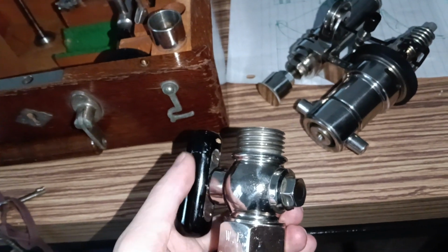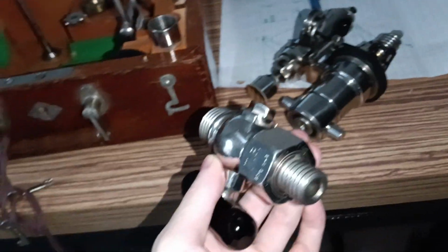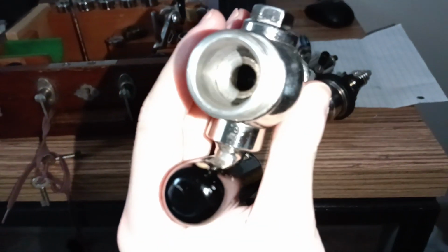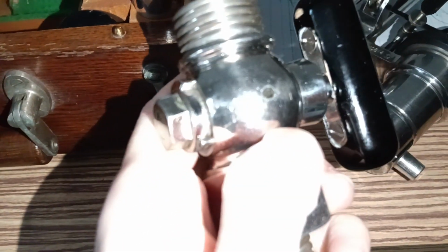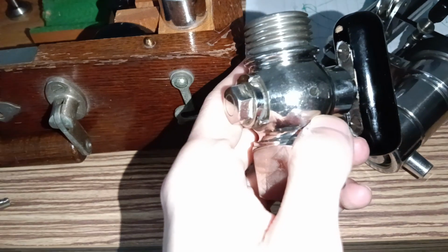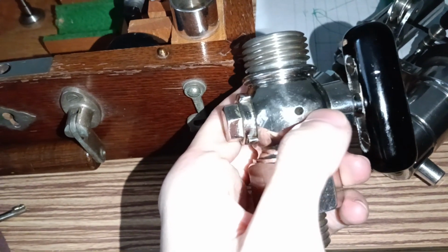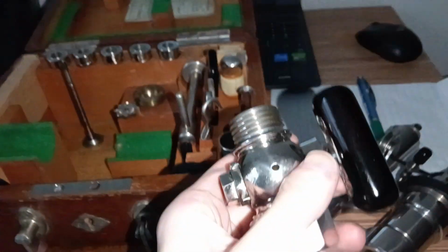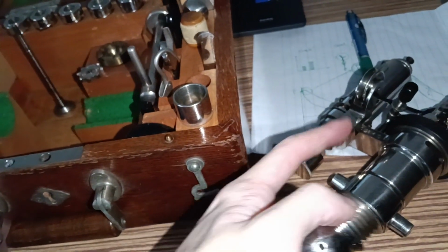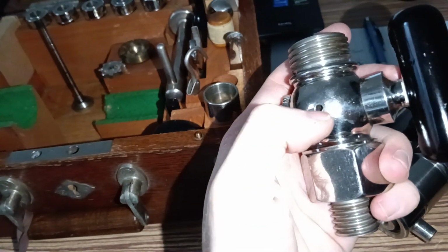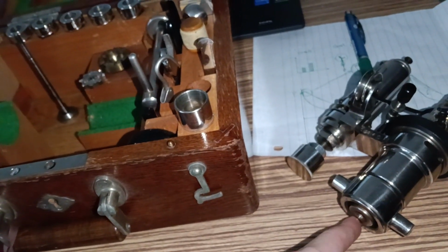When connecting, you connect this to the engine indicator cock first, this one to here, then open this one here. This is just another kind of indicating cock, but I don't really understand it. And actually the pressure releasing hole here, you can see this one here. Now it's open like this, and it's a ball valve.